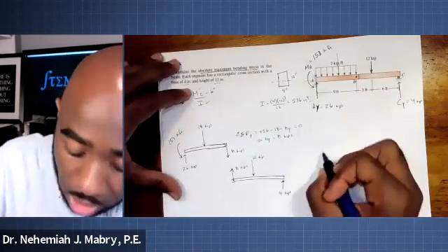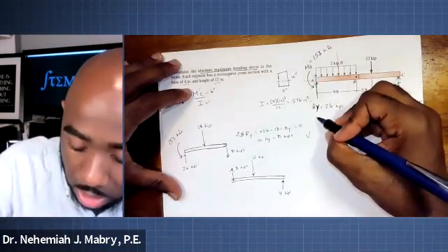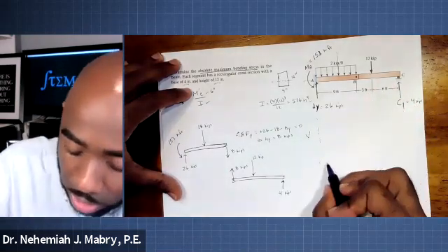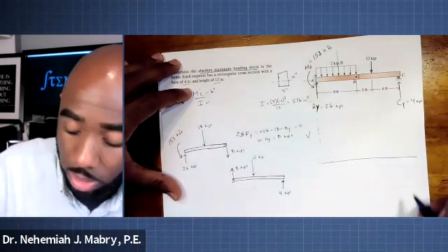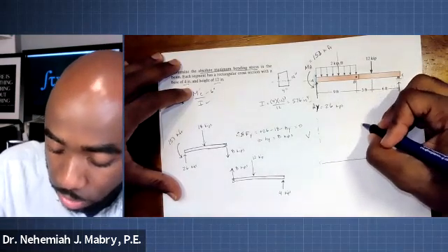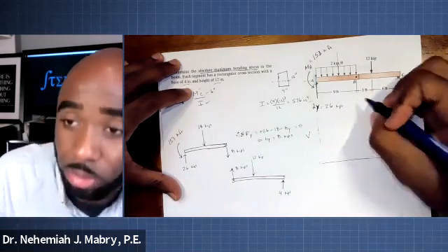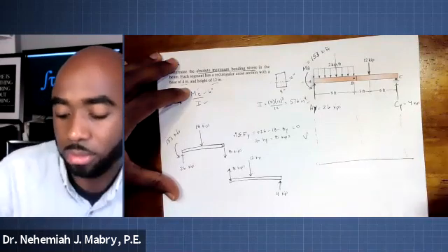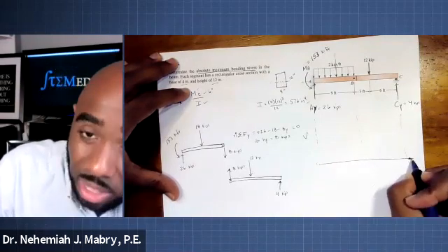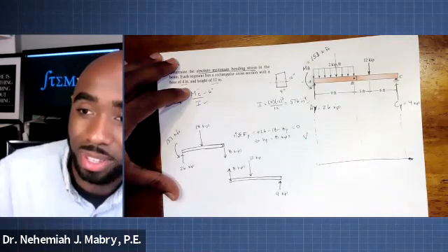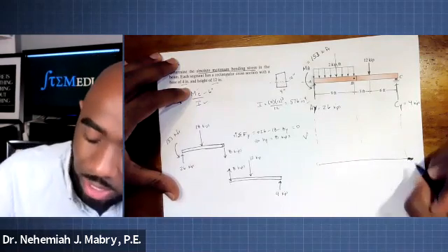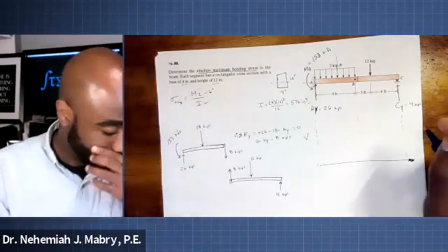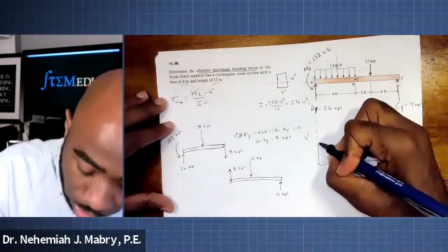So let's come over here and draw our shear diagram. One of the convenient ways is to always show how it lines right up with the diagram above it, so I'm drawing these small connection lines. Keep making it too long though. But anyway, that should give us an idea of what we're working with. Imagine that's not there. All right, here we go. Starting things off, 26 kips, 26 kips. So we're going up 26 kips.